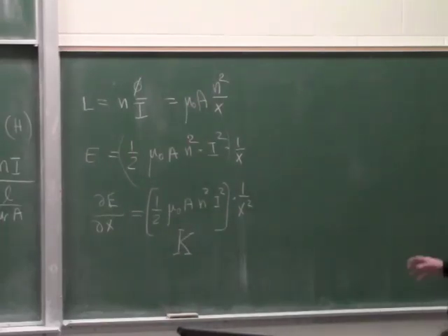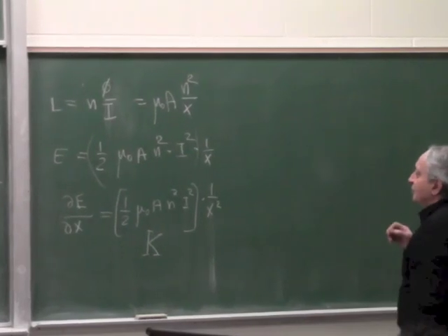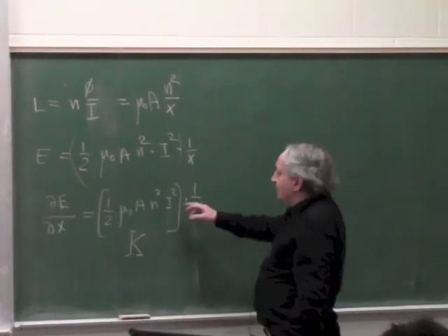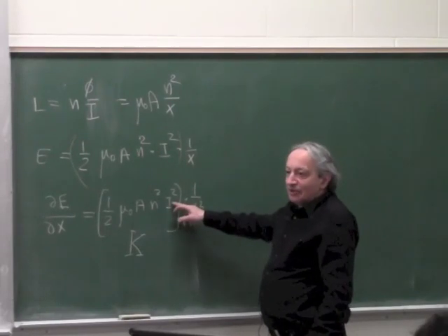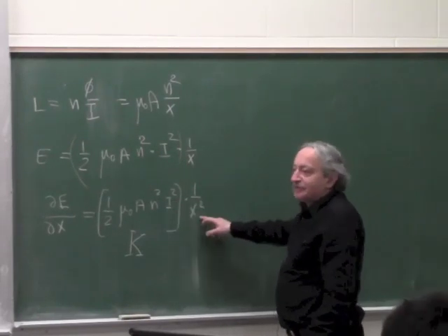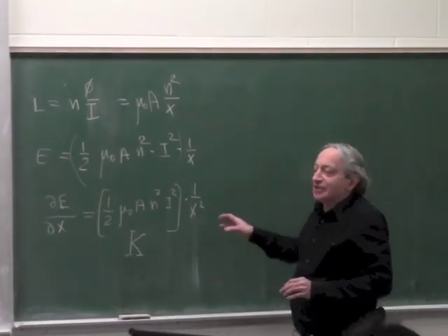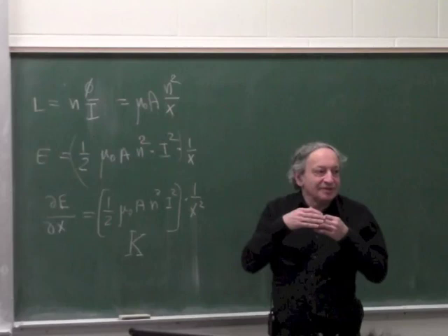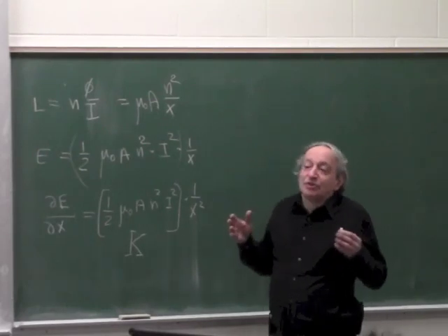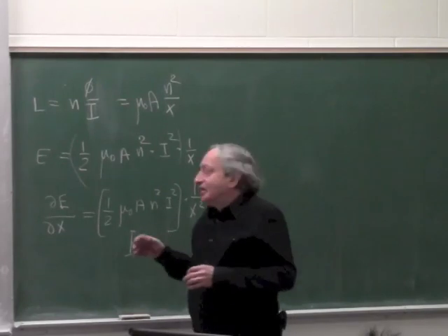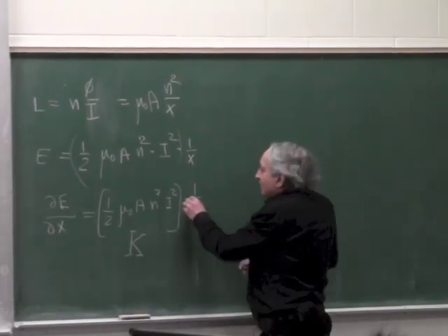So basically, if we take an electromagnet, the force is not going to be linear with current or distance. It's going to be square with the current, nonlinear with current, and inverse square with the distance. But all this just means it's nonlinear. All this doesn't explain snap, because the fact that it's nonlinear is not such a big problem. It's not good in a servo system when actuators are not linear, but it doesn't mean they can't be used.